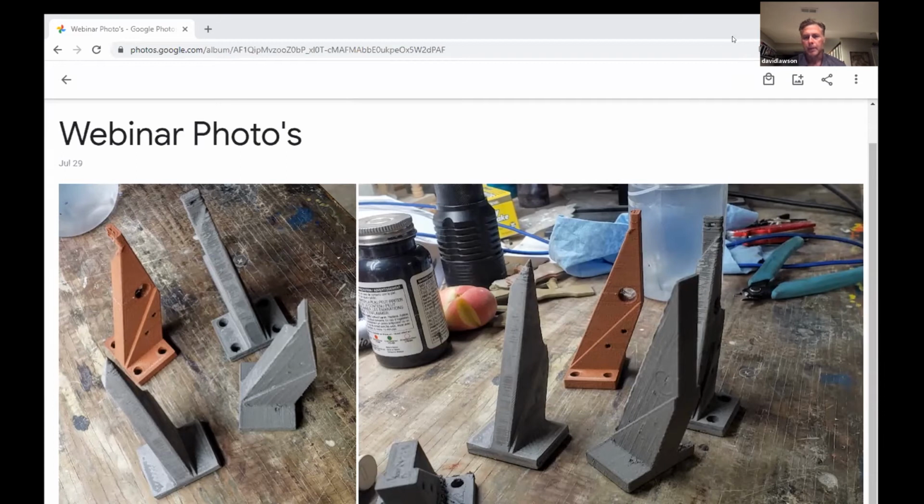Also, Trish, you mentioned for example, on this part, it looks like there's a piece that maybe is a stop or something like that. If that face needs to be perfectly machined, you can do that after sintering. Yeah, you can also machine before sintering.